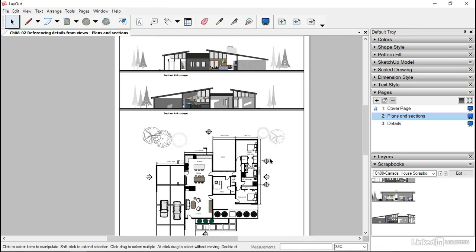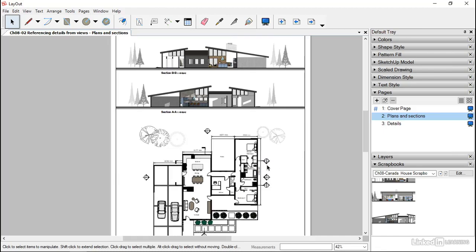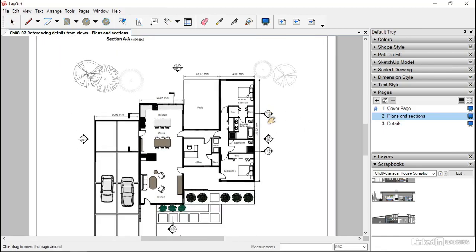So I've got 3 section slices on this drawing. Only 2 of them are on this sheet. The third one sits in here, that's section CC. But this one, section AA, I think this is, or BB, this one. Let's zoom in a bit. So section BB is cut through here, and it's looking in this direction. This pointed bit here means that the direction of travel for this view is this one. And section AA is looking back that way.